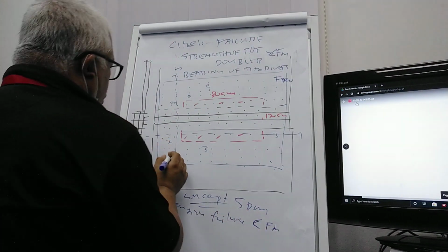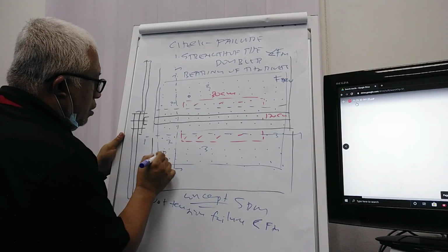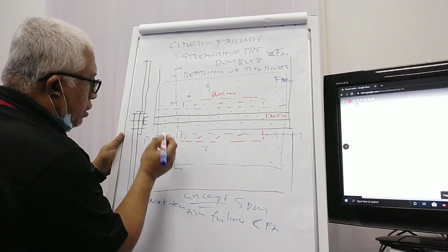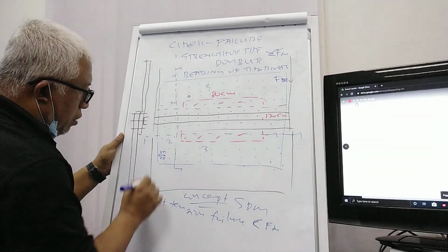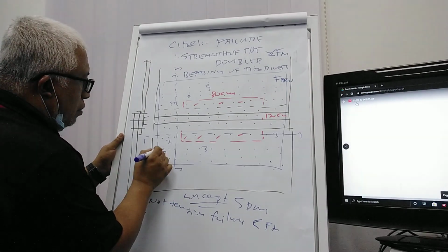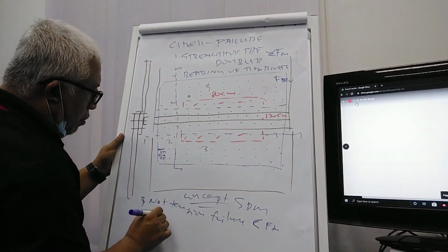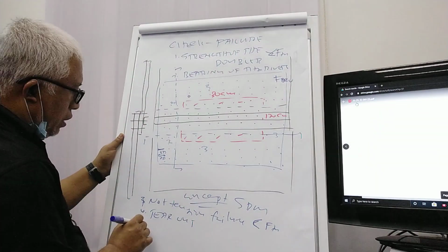And then you check on the shear out. Here is H distance. H distance is normally 2D, but whether this 2D is sufficient or not, you check on what is the failure here: this rivet will migrate out. So we call that tear out. I will do the detail later.